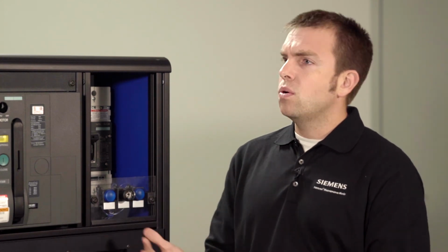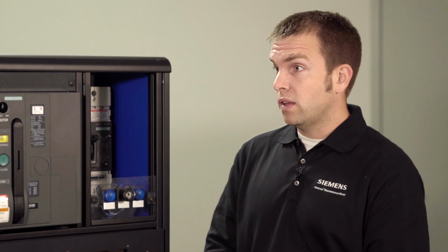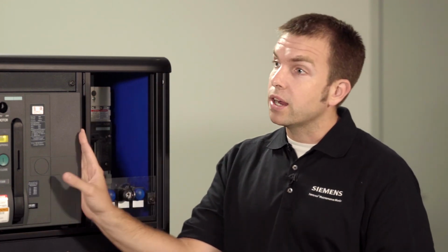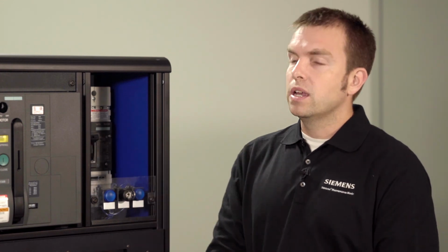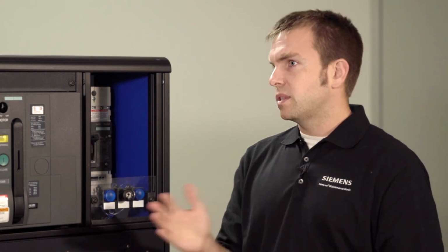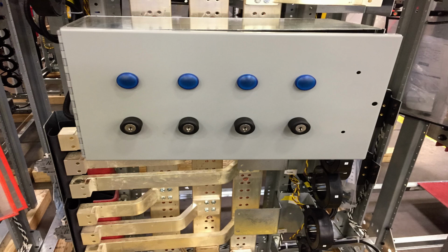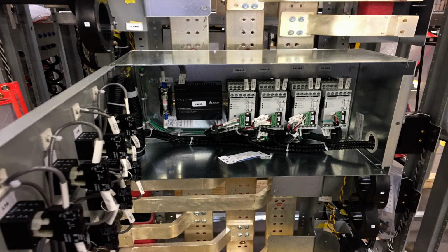And then we saw as the code adapted over the years that we need to have a solution not only for our WL circuit breakers like right here, but also for our molded case circuit breakers like the VL breaker like here. So a lot of them are 1200 and 1600 amps as well. Okay. So what Smart DAS is, it takes the same features that we have at WL, where you can adjust the short time and instantaneous, and it adds that feature to the VL breaker. So now you can adjust the settings to whatever you need.